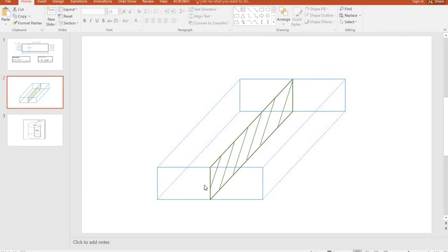In this kind of problem, we can take a rectangular cross section in the middle and do a 2D analysis, which would give us good numerical results. Why? Because near the wall there will be shear stress, or resistance to the flow, building up opposite to the flow direction. But in the rectangular channel, the side walls are far away from the middle, right? So if we take a cross section at the middle and do a 2D analysis, the resistance from the side walls to the middle section will be really negligible.